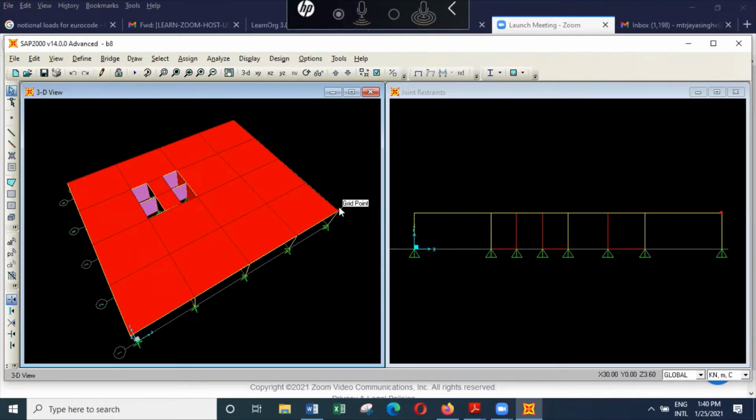On the other hand, if you have a pile foundation with, say, four piles per column, any bending moment can also be resisted by the group of piles, so there is no harm in considering that it's fixed at the ground. That will all depend on the type of foundation you have. And let's say you have an inverted T-type shallow foundation, with say 1.2 or 1.5 meter deep beams